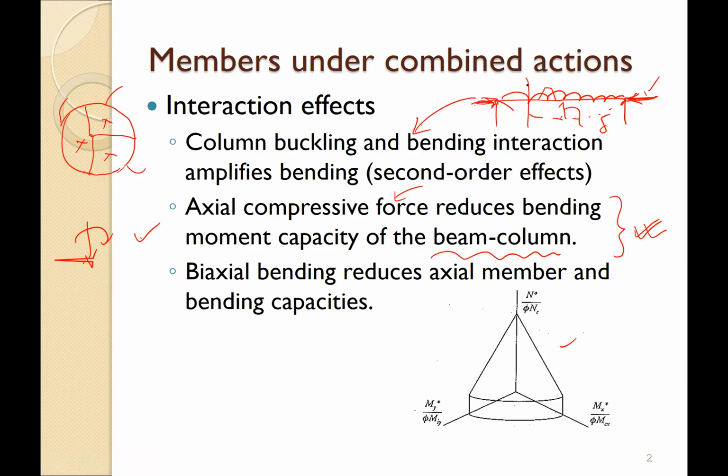If you cut a section and then draw the shear force and bending moment, you will actually find that if you write d squared y over dx squared equals whatever, the one will be the M, which is the effect of the bending. That means you have a reaction, then you have Rx minus Wx squared divided by 2. Say this is your moment M. Then you have another component which is due to the axial force. That means that will also produce a moment.